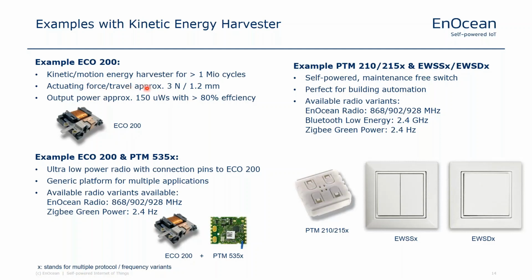The actuation power is 3 Newton, and the travel is very low, 1.2 millimeter, to be very flat in this case. The average power output is 150 microwatt seconds. I have already mentioned the range before, and the efficiency of more than 80% getting out of this. So we offer some combinations with radio modules.